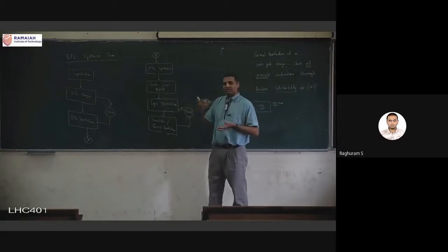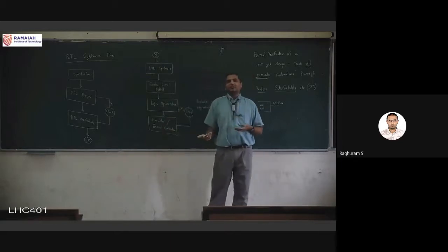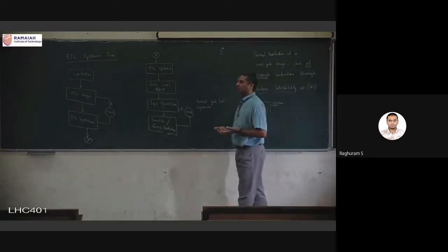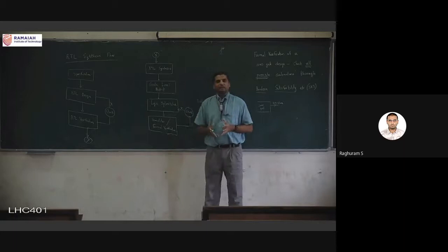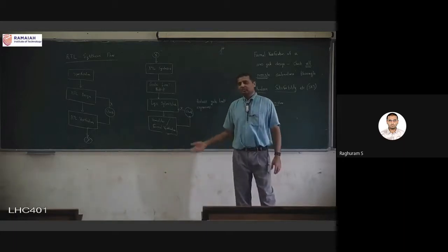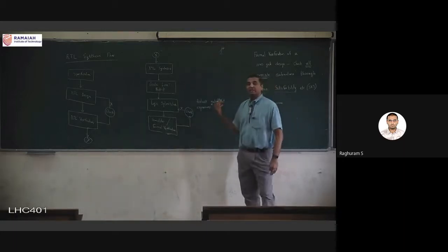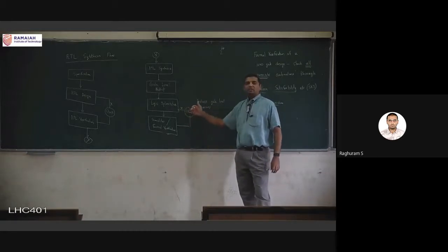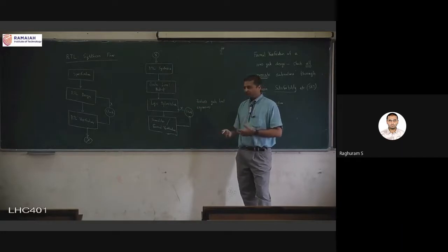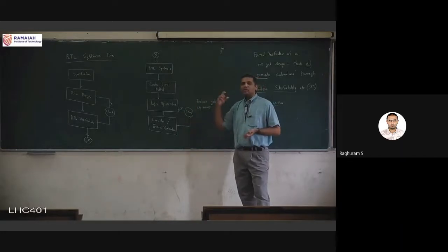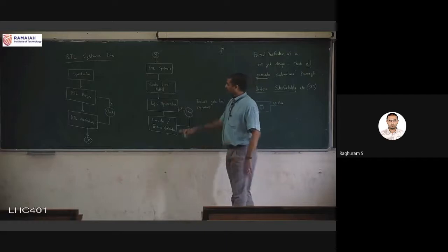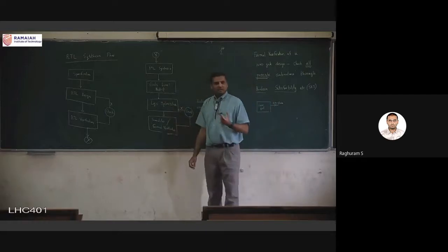The reason is the design is continuously getting transformed, and of course the tools, as far as possible, will try to maintain the functionality, but because these designs are so large, something could happen that the functionality is misunderstood or lost. So that is why it's important to check it after every transformation. And verification is the majority of the time, 70% of the time in the VLSI design flow goes to these verification steps. Okay, so after this, we are sure that the logic is fine.